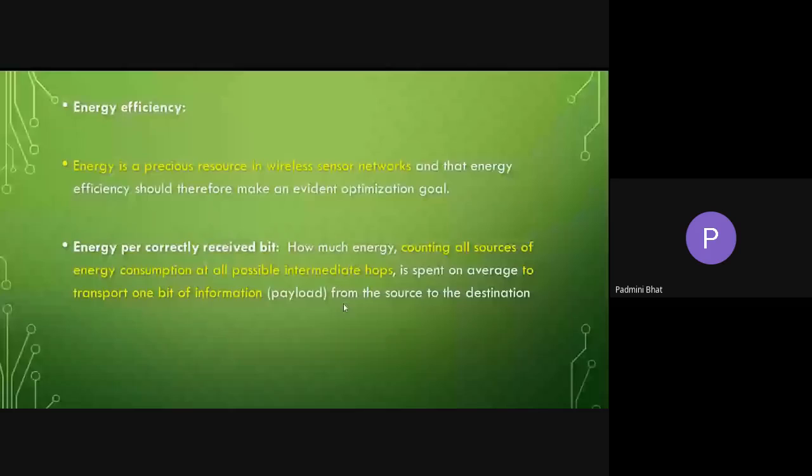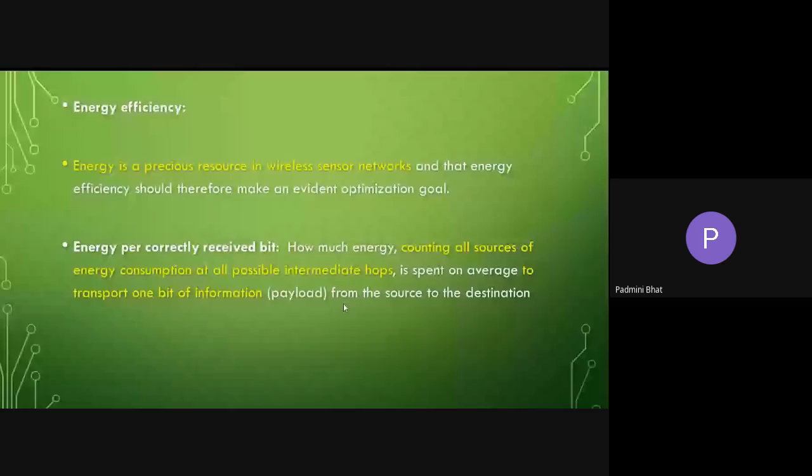When I'm using three nodes, the cost, in the sense, it has to receive this from node A, it has to process. For that, energy is required, right? Whose energy? Node C's energy is being utilized for that. If I could transmit A to B directly, then C would have spent that energy for some other purpose. Now, just to transmit from A to B, C is utilizing some power, C is sending, D is utilizing some of its power. So that is power budget calculation.